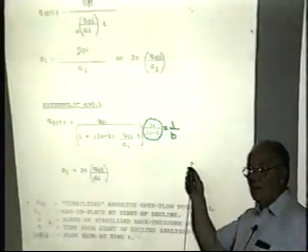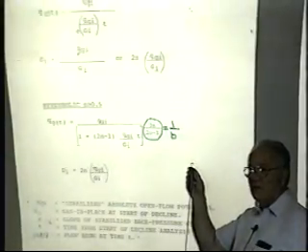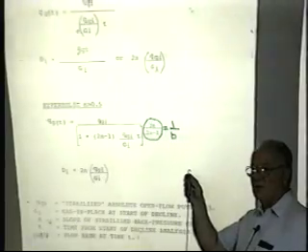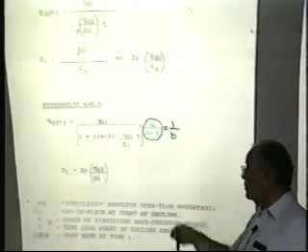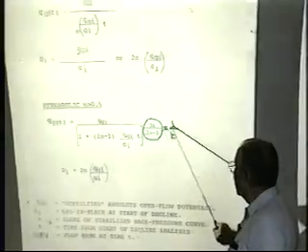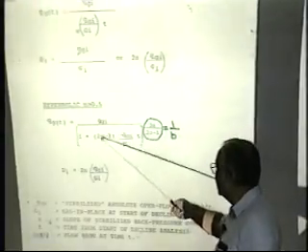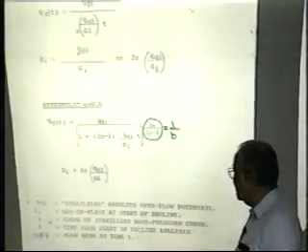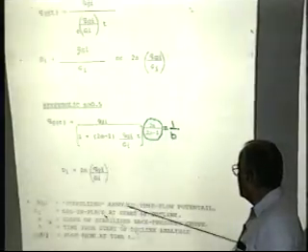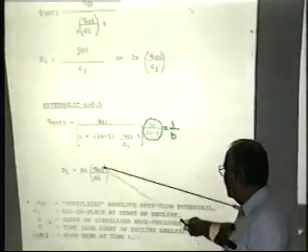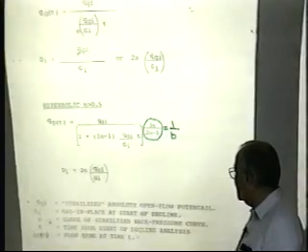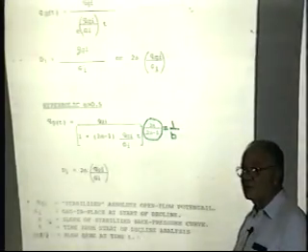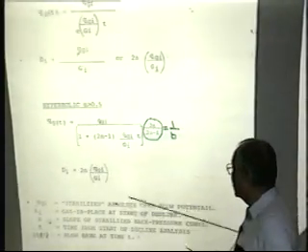So that I'll either calculate the slope from reservoir parameters where I don't have performance data, or if I have performance data, I can predict the value of B, and I can predict the value of D sub I. Remember again that the QGI is the rate off of the stabilized curve, or pseudo-steady state curve.